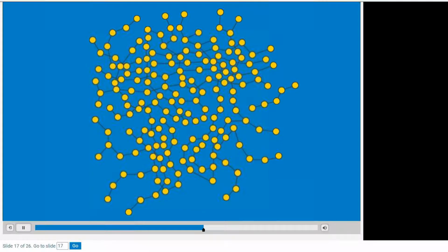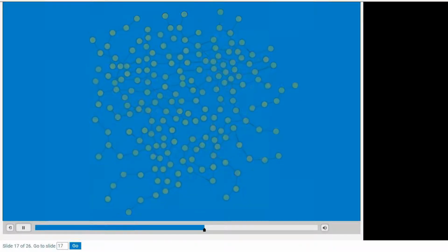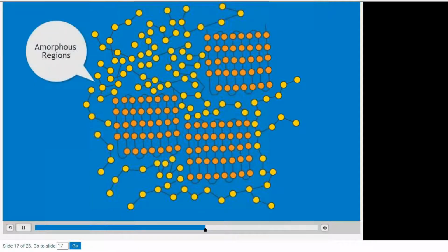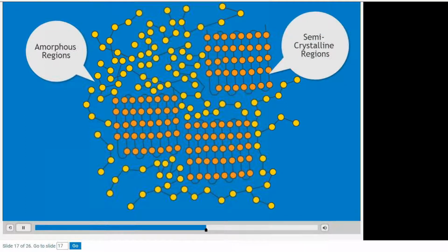Amorphous materials have no directional properties. Although semi-crystalline materials also have some amorphous regions, they contain mostly crystallized areas. This may result in directional properties that could cause inconsistencies in part properties, in addition to shrinkage and warpage behaviors.